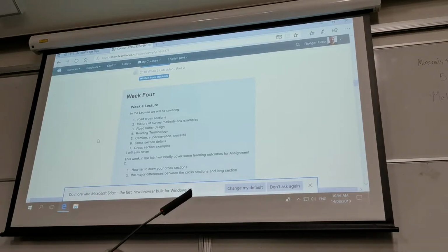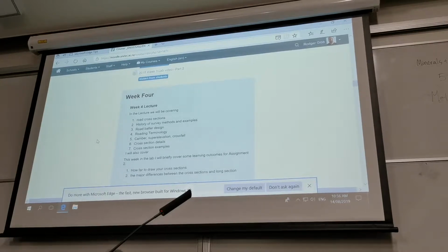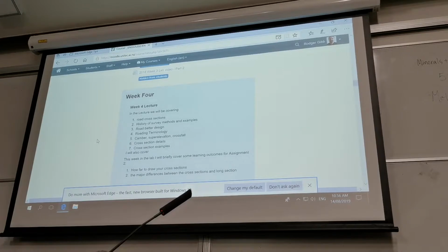Second cheapest option is, if the geotechnical engineer won't let you change the batter slope, then you're going to have to put a retaining wall there. Once again, you're not engineers who design that. The surveyors definitely aren't. So you need to put a note saying engineer to design retaining wall. Structure engineering, very good, well done.